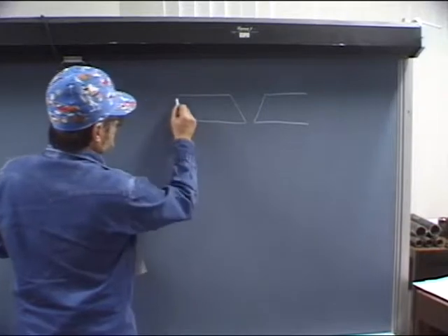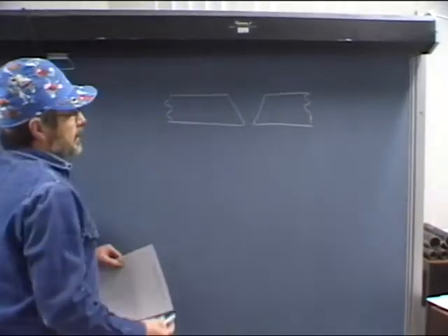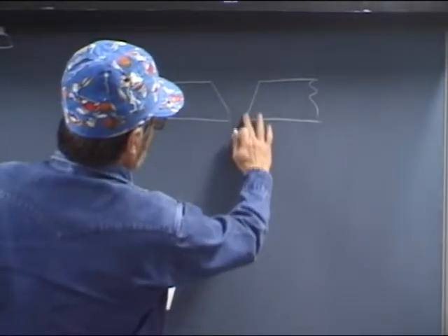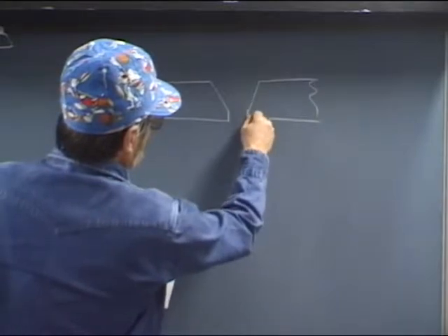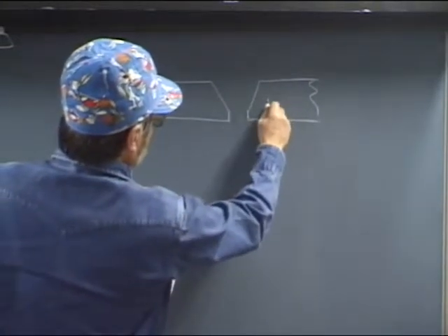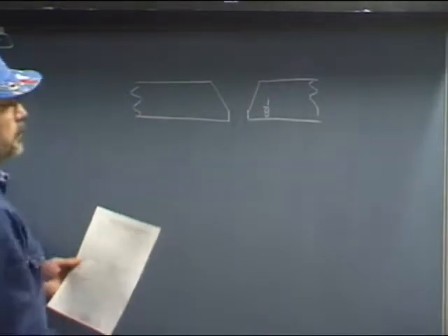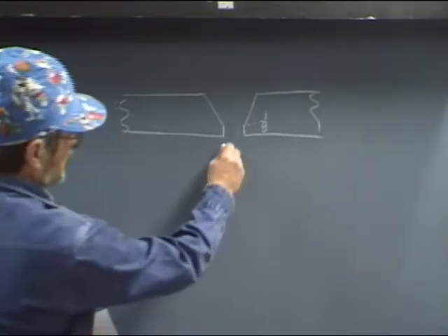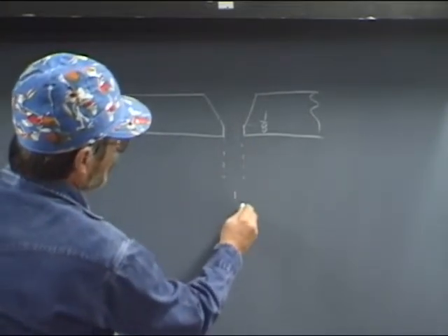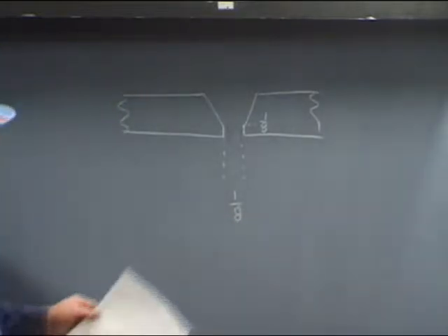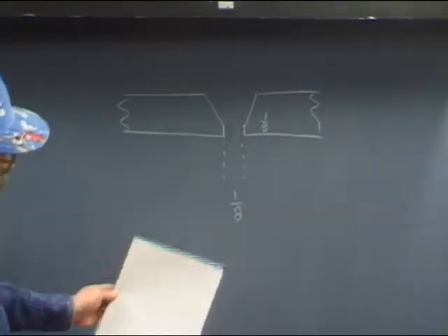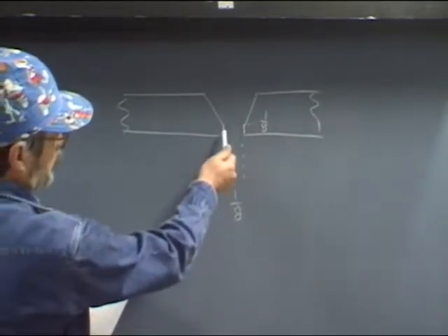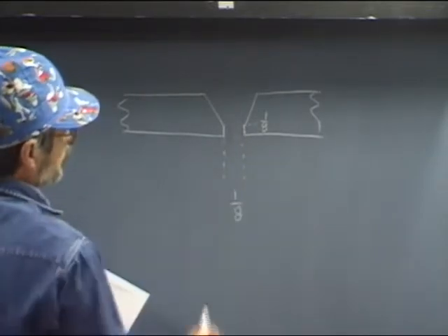And we're going to draw that in there, but if we told that welder, well, we want to have a root face that is 1/8 of an inch, then we have to record on our drawing 1/8 of an inch for the root face. And if we had a root opening of 1/8 of an inch, then we would have to draw in that space 1/8 of an inch, so that whoever's looking at this knows that this test specimen was made with a 1/8 inch root face and a 1/8 inch root opening.